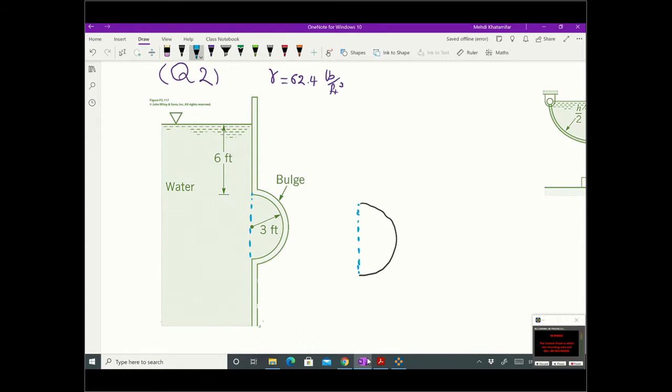First I'm going to have weight applied at the center of gravity. Let's call it W. And from the water, I'm going to have a pressure force from the left side. Let's use F_R and red color for that. And those two, vertical and horizontal forces, must be nullified with some F_H and F_V forces, otherwise it's going to move.